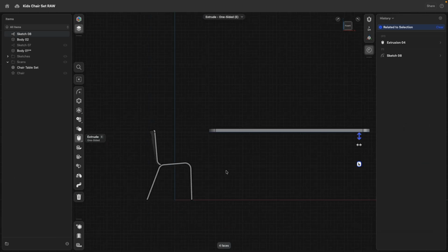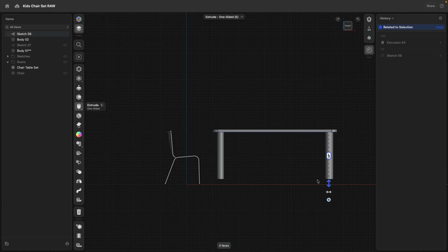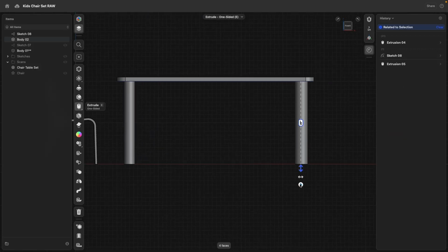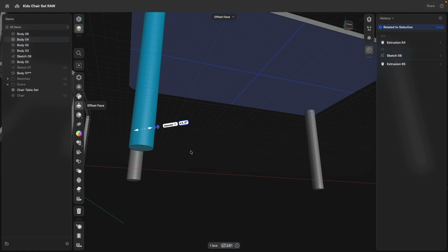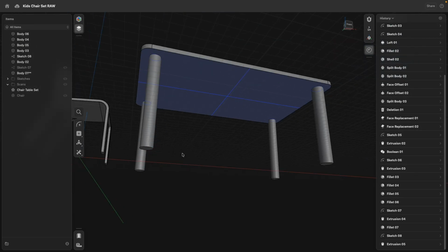four circles, and then we extrude them down. Should be 20 and 21 on top, 1 inch material thickness, 20 down. But we want those as new body. Very good. They look really thick now.